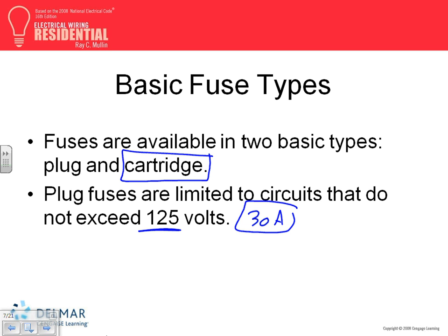Tiny little loads, for example, are commonly used. Guys, if you have a garage door opener and you need to protect the motor of the garage door opener, you need specific protection for the motor. So you have this box, a tiny little plug-in fuse, and you size the fuse small enough to protect the garage door opener. For the most part, guys, unless you're an electrician, you really are not going to be doing a lot with the plug-in fuses. Cartridge fuses are your babies.